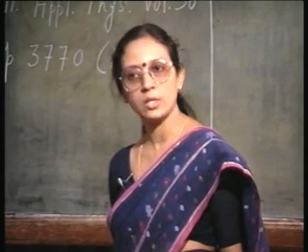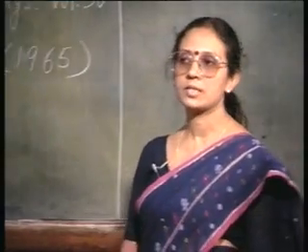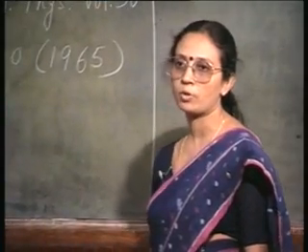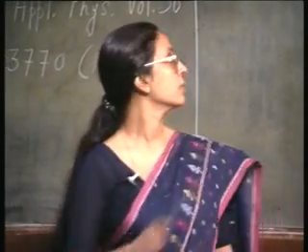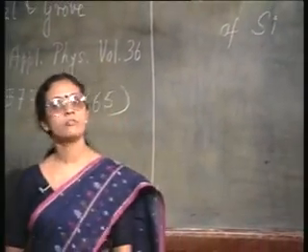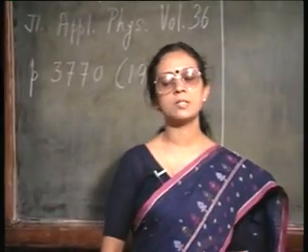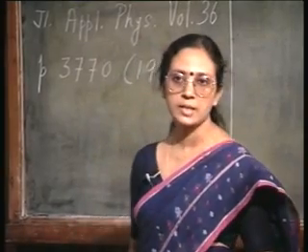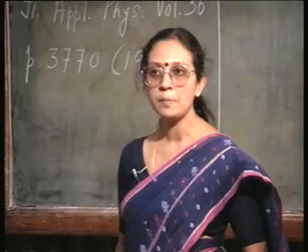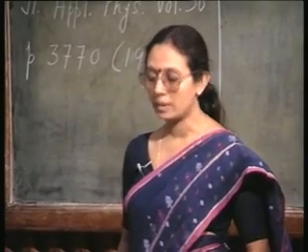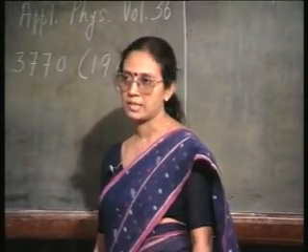that is called anodic oxidation. But the most important oxidation technique, most important from the point of view of VLSI technology, is thermal oxidation of silicon. The quality of thermal oxidation is by far the best. Of all the oxides that is grown on silicon, the quality of thermal oxide is the best, and therefore, thermal oxidation is widely used in VLSI technology.